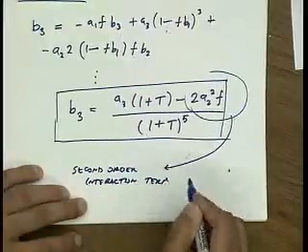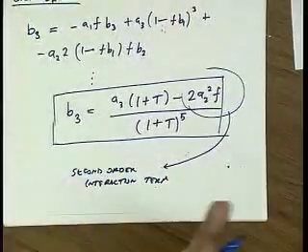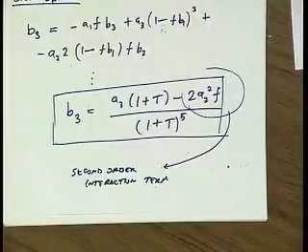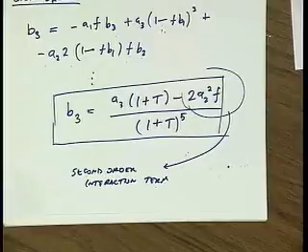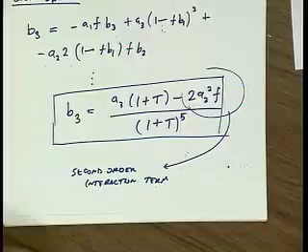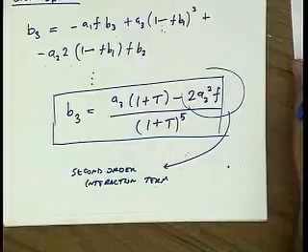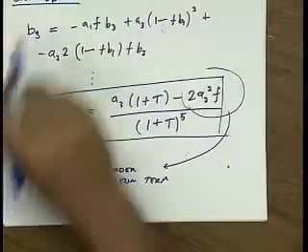Remember last lecture we talked about a FET, and we said ideally a long channel FET has no cubic. But if there's any kind of feedback in that FET, for instance, source resistance, shunt feedback through that Miller capacitor, if there's any kind of feedback, which in reality there's going to be, then second order interaction will generate cubic distortion. Okay?